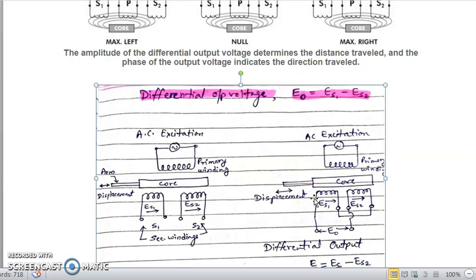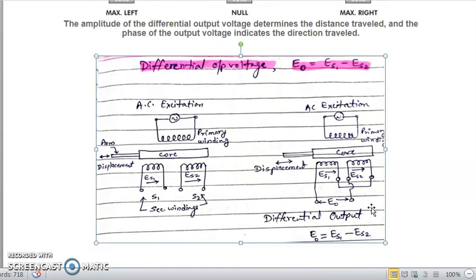Okay. Now if they are in series connection, what will happen? The first winding's negative should be connected with the second winding's positive. This is the series connection, when series connection is in phase. But when it is connected in series opposition, as I have told you, the rightmost of secondary 2 is at positive, and the right side of secondary 1 is also positive. So now what we are watching is that both the positive terminals are connected.